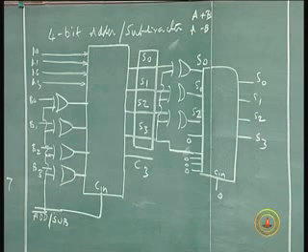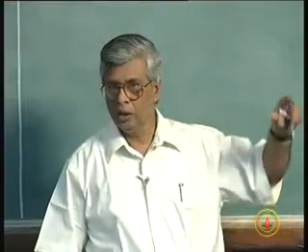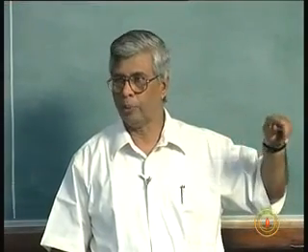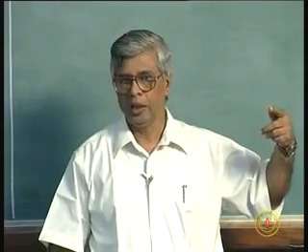We said how 2's complement addition is the same as subtraction. We also saw how a common hardware adder can be used for 2's complement addition as well as subtraction by taking the 2's complement of the number to be subtracted.